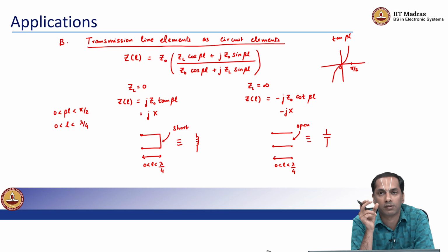And these, if placed at appropriate locations, can radically change the behavior of the circuit. So you might see floating structures that are branching off from the main transmission line that's carrying the signal, which may indicate that you have some sort of a capacitor or an inductor that they are trying to emulate.